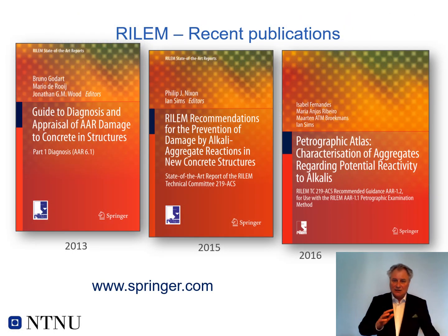So this was the Norwegian approach, and we are using that, and we are feeling quite confident that it's working very well in Norway. With the worst case aggregate, we are able to put some critical limits for the different cement used and so on. And in that sense, we are making durable concrete in Norway, even though we are using alkali reactive aggregates.